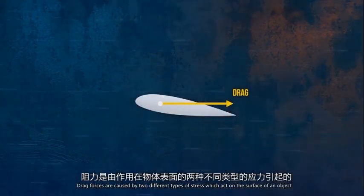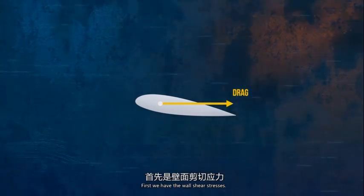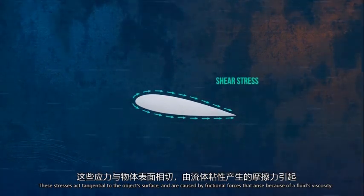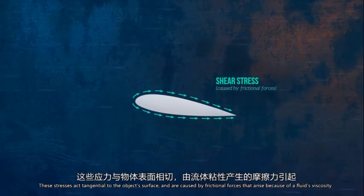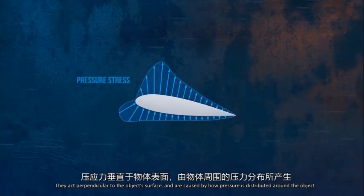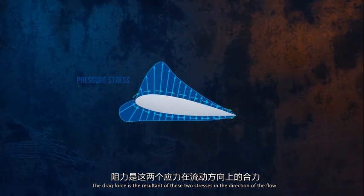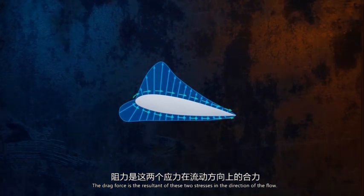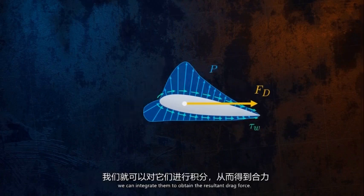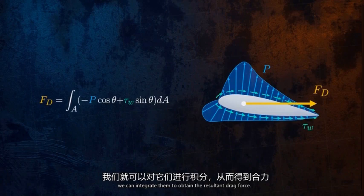Drag forces are caused by two different types of stress, which act on the surface of an object. First, we have the wall shear stresses. These stresses act tangential to the object's surface, and are caused by frictional forces that arise because of a fluid's viscosity. Then we have the pressure stresses. They act perpendicular to the object's surface, and are caused by how pressure is distributed around the object. The drag force is the resultant of these two stresses in the direction of the flow. So if we know exactly how the stresses are distributed over the surface of our object, we can integrate them to obtain the resultant drag force.